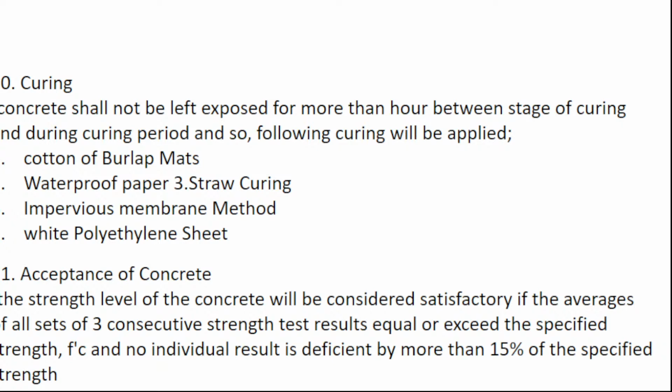Curing. Concrete shall not be left exposed for more than an hour between the stages of curing and during the curing period. So the following curing methods will be applied: burlap mats or burlap cloth, waterproof paper, straw curing. So using straw, put it on top of the pavement, impervious membrane method, and white polyethylene sheet. Okay, to maintain the moisture level and maintain the homogeneous curing of the whole cross section of the road at the same time.